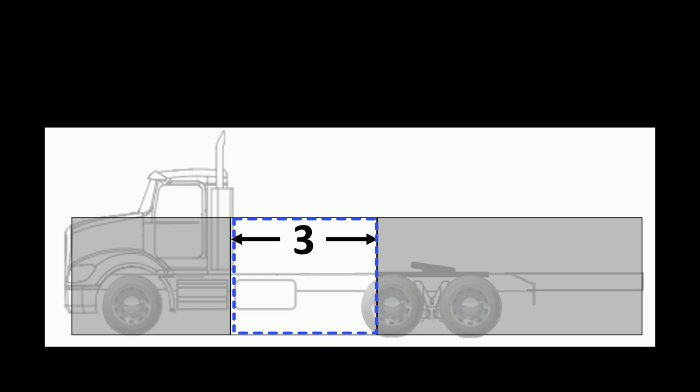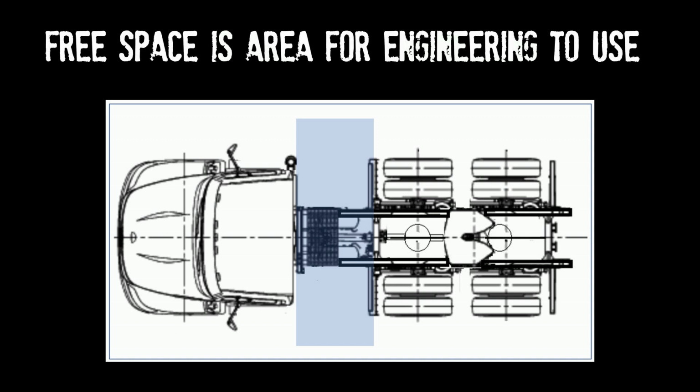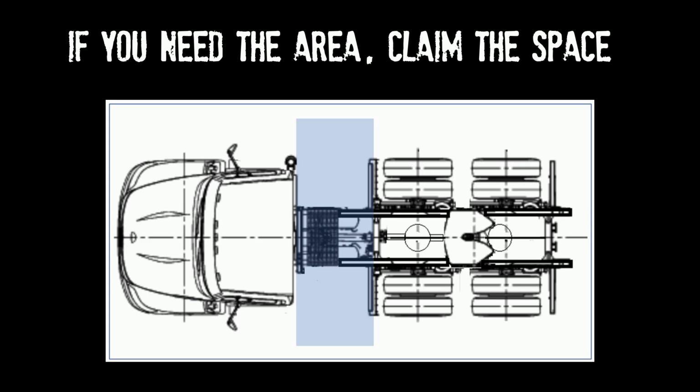Understanding region complexity helps optimize chassis design. Even with lower complexity, the back of cab to rear suspension is where engineering fits air components. As such, noticing a lack of componentry does not guarantee the area to be available to accommodate customer needs. Many OEMs have methods for communicating requirements for clear frame areas, which should be used when beneficial.